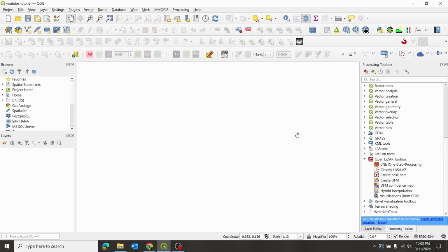Areas that it is good, it'll choose the best method of interpolation when creating this raster, whether to use inverse distance weighted or triangulated irregular network. I really like that it uses this hybrid model. I feel like it catches features, it models features better than doing one or the other. And so this is my method that I use.